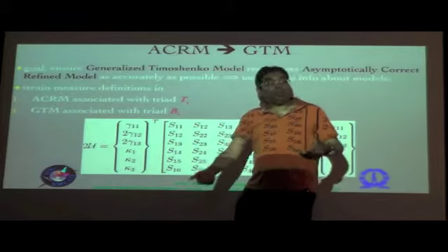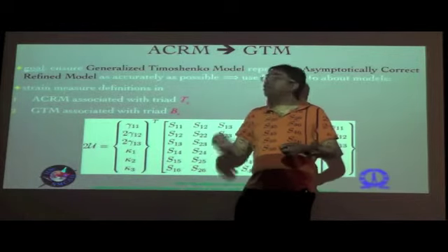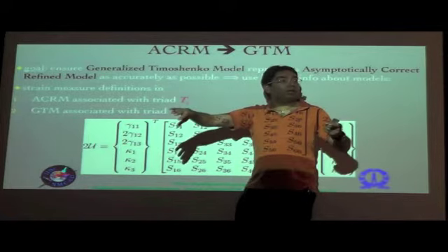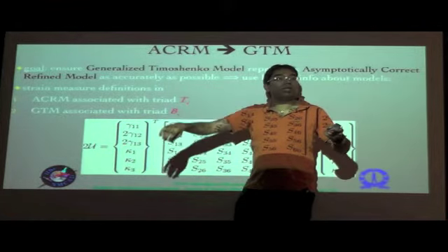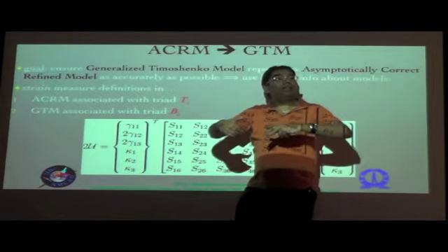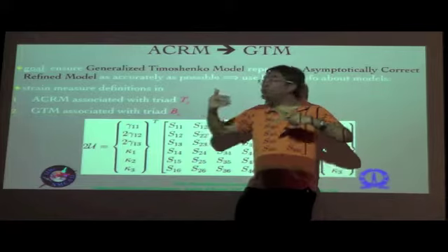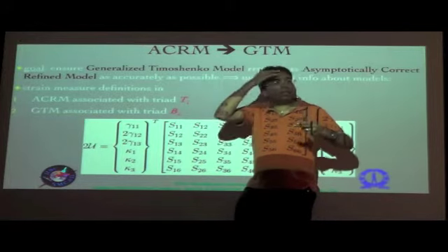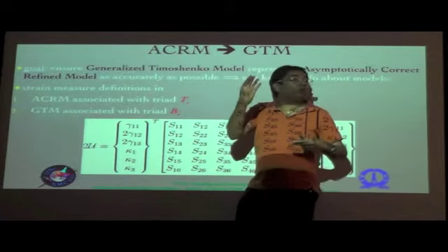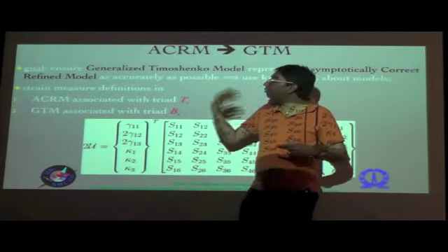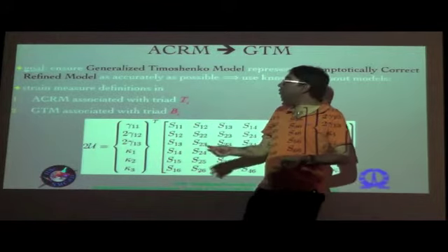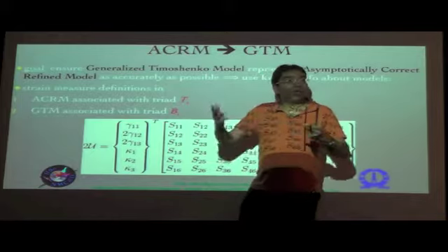Of course, the reason why we don't have that is basically because if you go to the so-called phantom step of the variational asymptotic method, where you can deal with all 3D quantities and then use the variational asymptotic method, which we didn't do there, which Berdichevsky has done in some of his initial papers of the VAM, there you would see that only 4 degrees of freedom were extracted, and therefore we basically stepped on from there to use only those 4 degrees of freedom, and that became quite convenient.